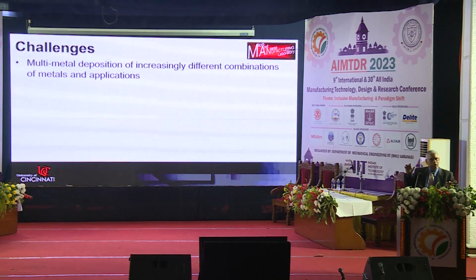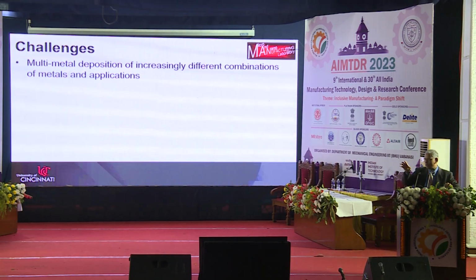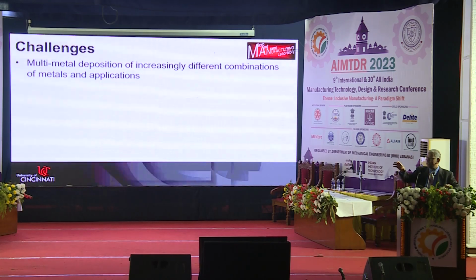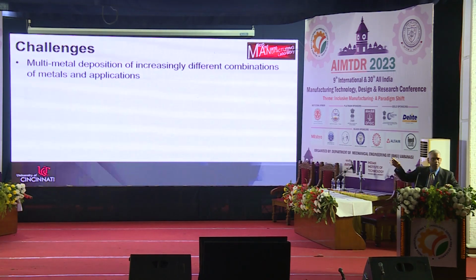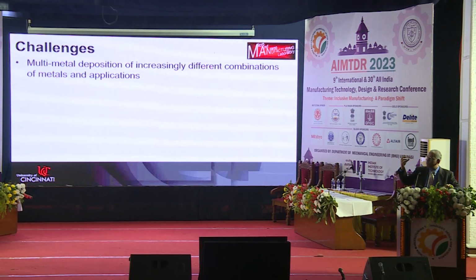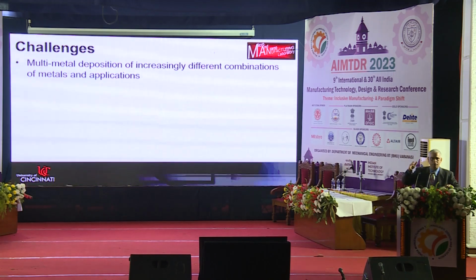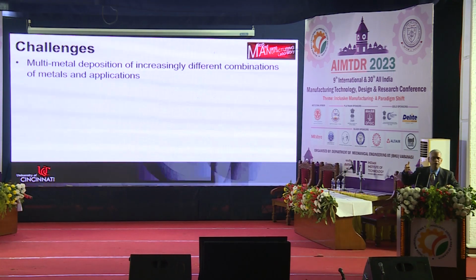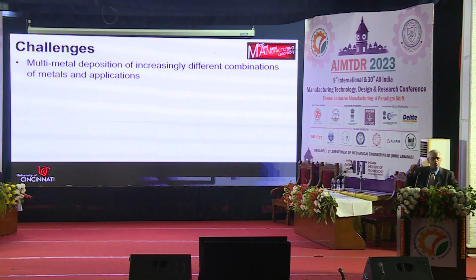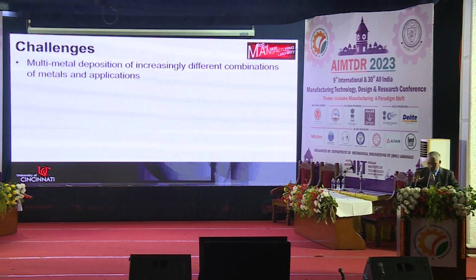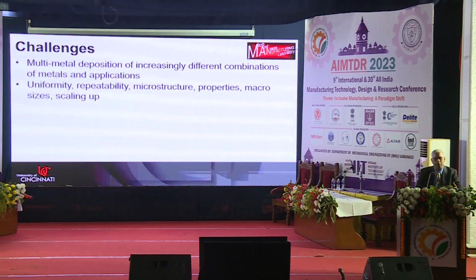It's not like a traditional process such as milling. In milling, I can classify materials as ductile or brittle, and the process parameters I fine-tune for ductile materials more or less work across them. So what I do for aluminum is likely to work for copper. Here it is not like that. For each material you have to come up with the right chemistry.